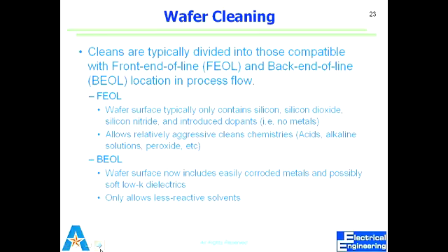Now, once I take it out, it's going to dry off. Acetone dries off very quickly. It will have residues of acetone in it. Now, what do I do with that? I dip it in methanol. Methanol is going to dissolve acetone, right? So acetone, I used it to dissolve any organic material, and methanol I use to remove acetone. After methanol, I can just rinse it with clean water. And that's a process called solvent clean.